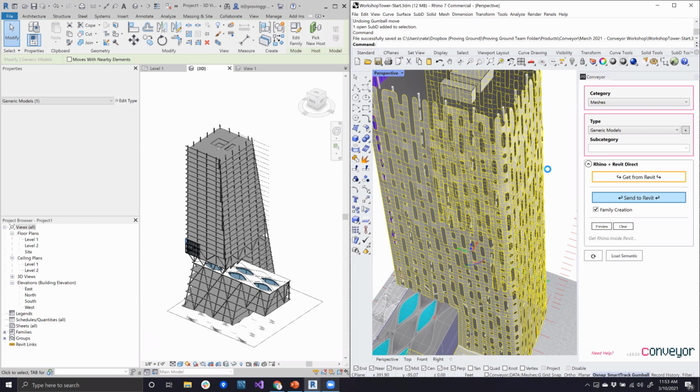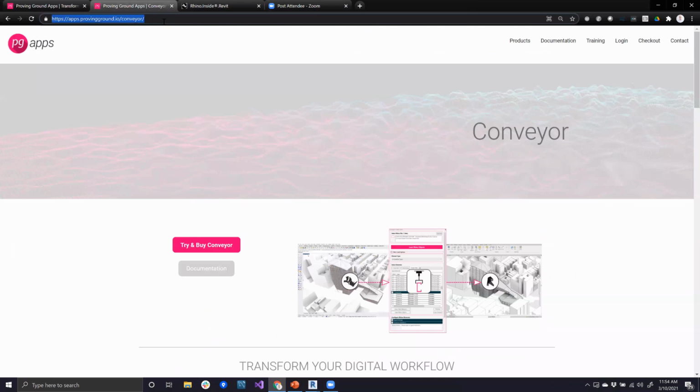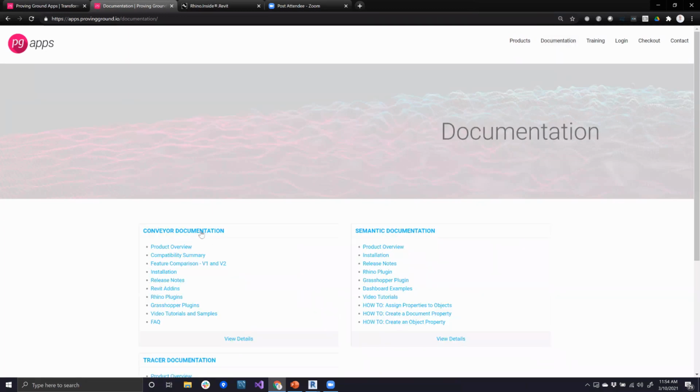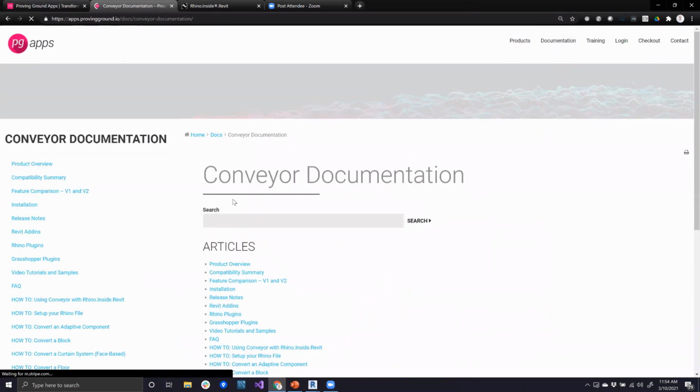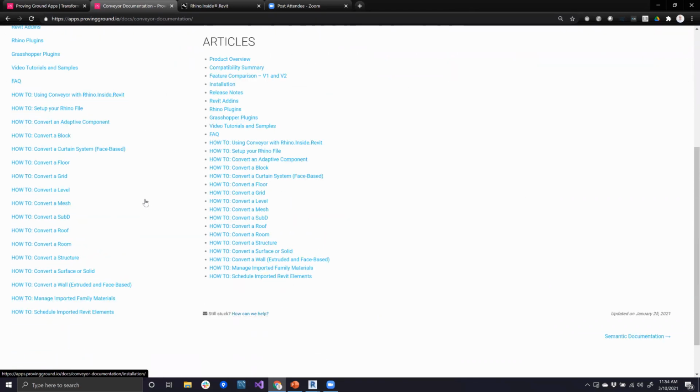While this is loading, Nate, I think it's a great time to answer one question about what geometry can be classified as different types of Revit categories or types. Yes. One common question we've had today was, when you were demonstrating the floors, there was a thickness to the floor in Rhino, but that didn't necessarily translate to the thickness of the floor in Revit because we specified a specific type that existed in Revit by typing that name in, right? But there are probably other limitations on types of geometry that can be assigned to floors or others, right?